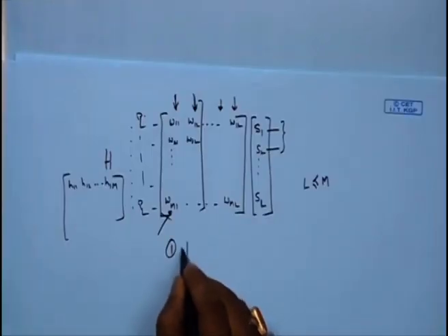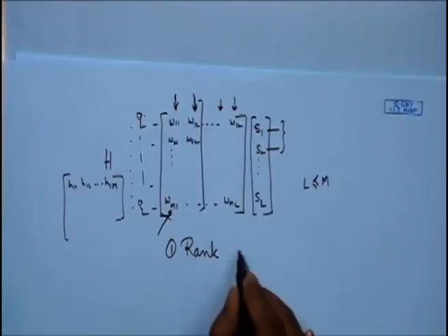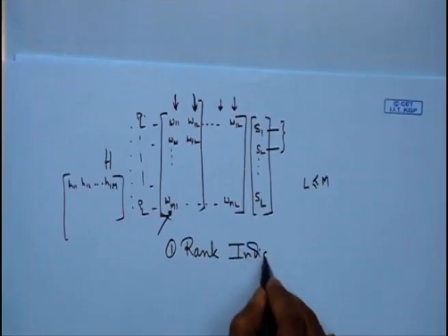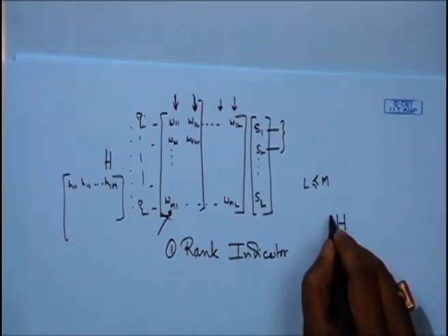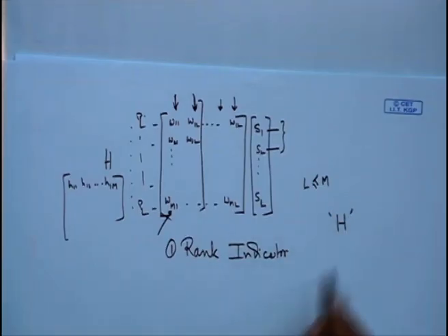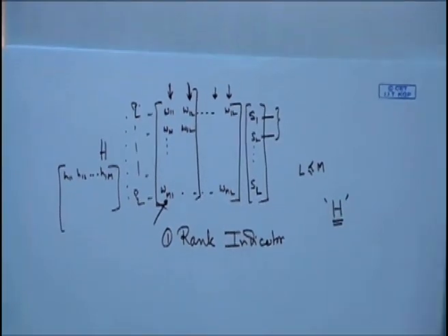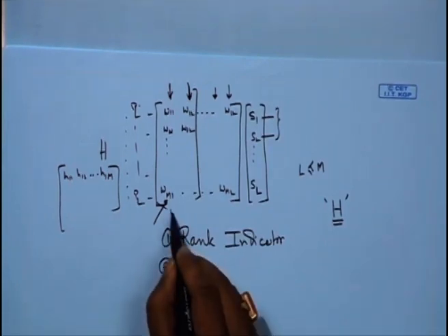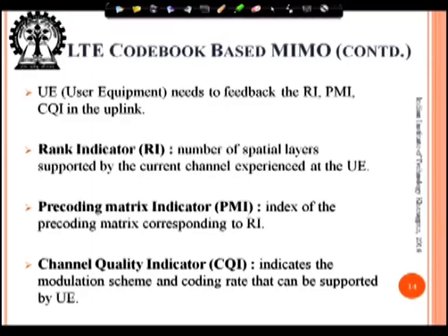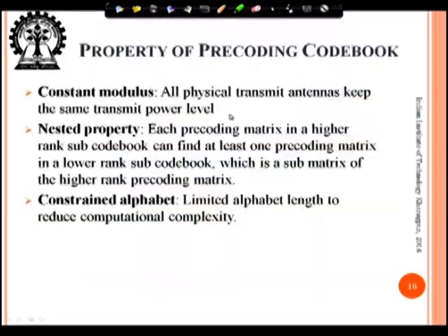So, for these systems to operate, the receiver needs to send to the transmitter not the full channel information, but the rank estimate of the channel, usually through a rank indicator. So, the receiver has to calculate the rank, and this is not a problem, because H is estimated at the receiver. This has to be done under any circumstance. Second thing, what the receiver should do is, these code books are predefined. I'll shortly show you the code books.